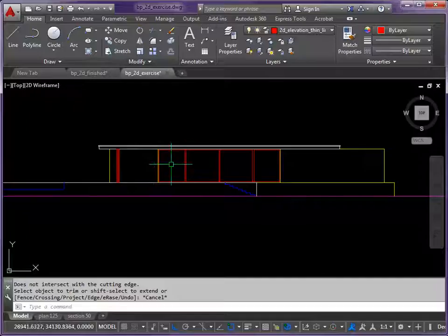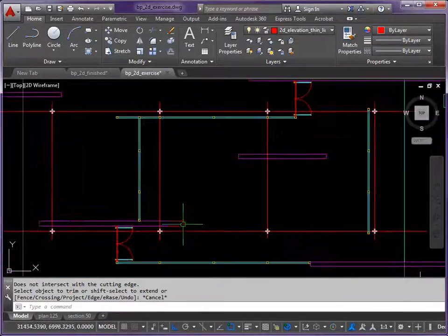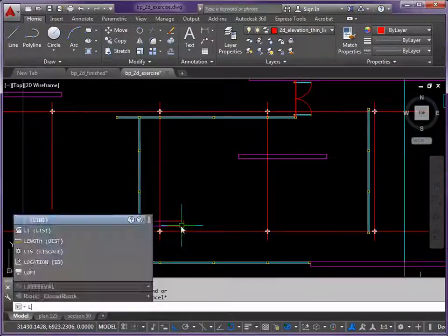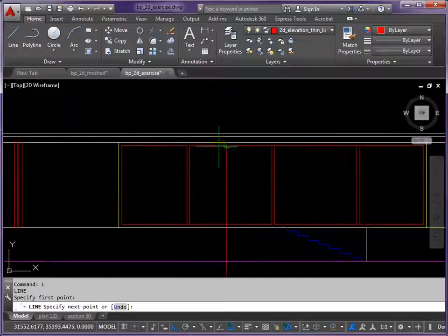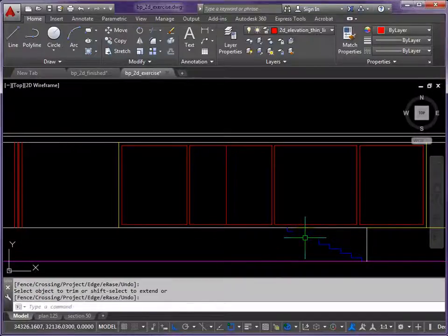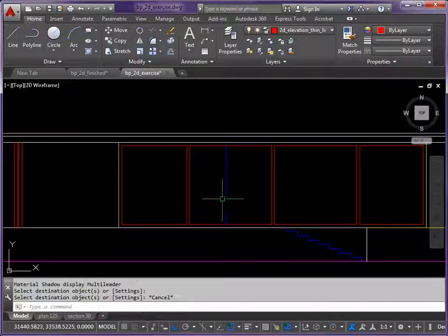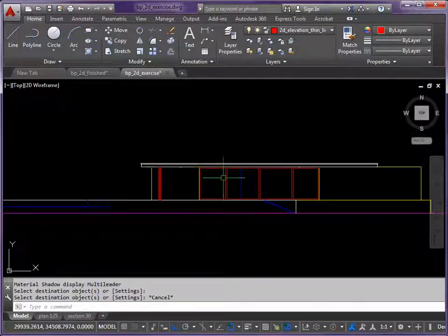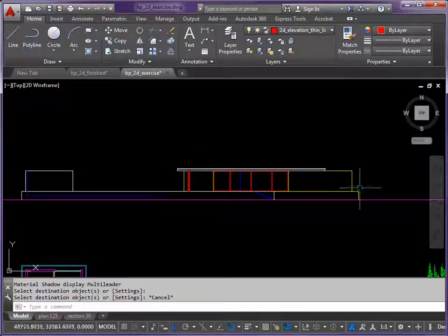Okay, this wall actually extends in to the building, so we'll just indicate that with a hidden line. So if we bring a line up from this position, it's just a little bit of detail that I would keep in. Trim that off using the window frame and then match it to the stairs. Okay, so it's just a bit further back, but it still might be visible through the windows. Okay, so that completes the architectural aspects of this side of the building.